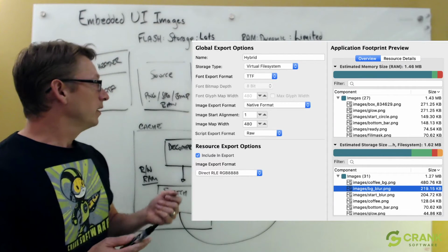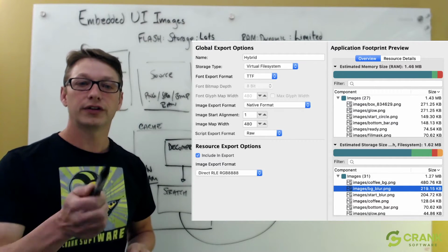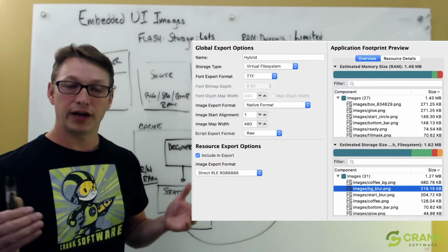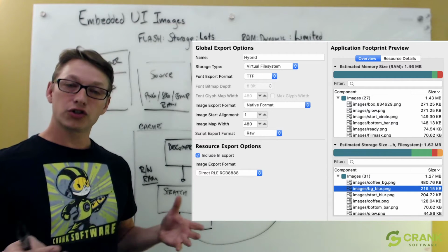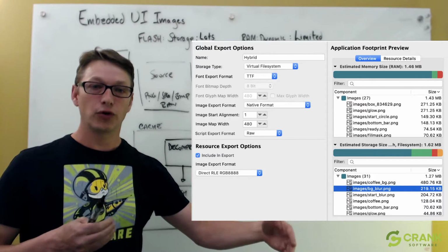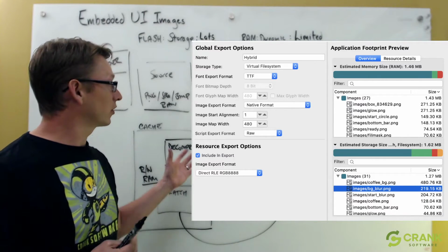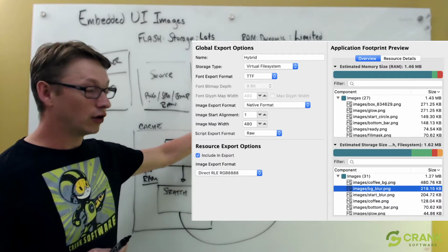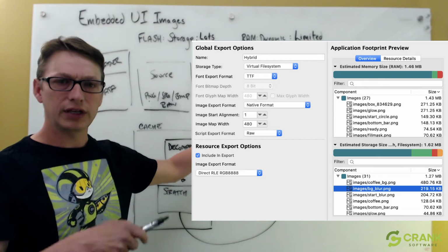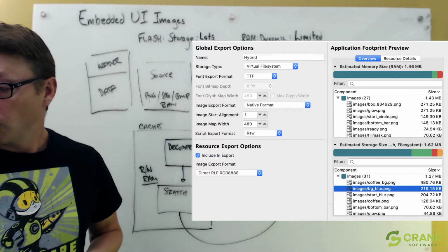The other piece that comes into this is our access time on Flash. When we're doing a lot of series of small little accesses, it's not always as fast in terms of the total throughput as it could be. So if I can put a larger image into Flash and get a long run of Flash read access, then I'm going to really hit my maximum performance on the Flash side, which is important, right? Because our total scene composition involves rendering a number of different images and compositing them together and putting them into this final display.